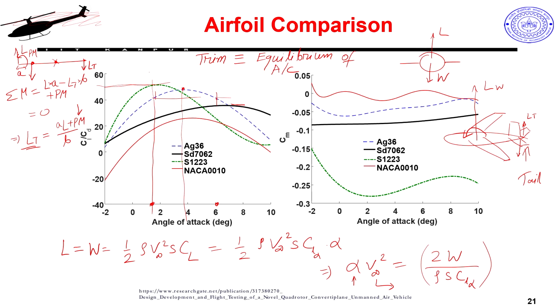So, this clearly now eliminates this green line. It says this is actually almost 2.5 times my black line, which is HD 7062, and compared to blue it is almost 5 times higher pitch moment. So, this tells me this is not a good choice for me.